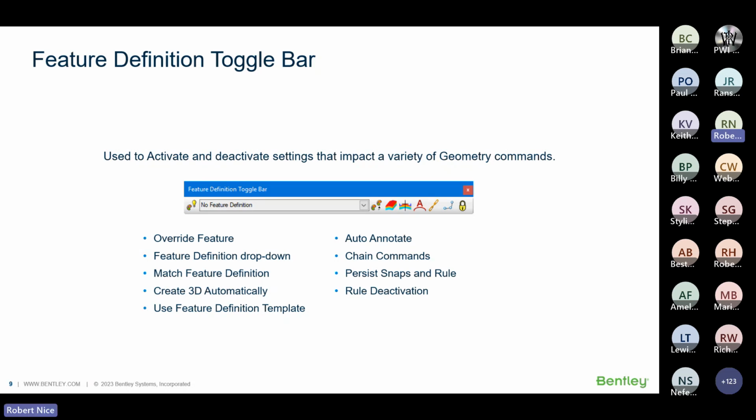And again, think of an annotation group like a preference. So maybe if I'm placing a piece of geometry, I could put in an annotation group which says just put in, I don't know, dumbbells at the cardinal points, or dumbbells and direction arrows, or give me just hash marks every 50 meters for change markers. If that is attached to it and auto annotate is on, that's what it will do.